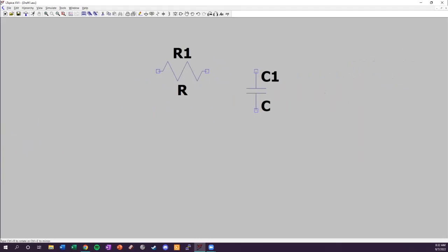And place this down right here by the resistor. And you can press V for voltage. So put your voltage source. And like with any LTSpice circuit, you're going to want to place a ground, because your circuit will not run